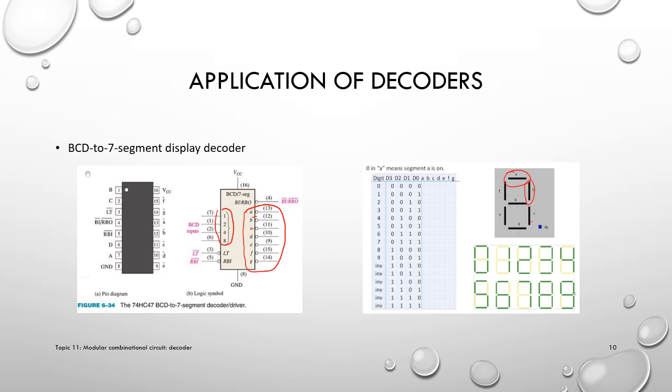Then we can realize this circuit using logic gates with no problem. So let's see how this works. For this 7-segment display, if we want to display the digits from 0 to 9, here shows which LEDs should be on in each case. So we can figure out the truth table based on this.